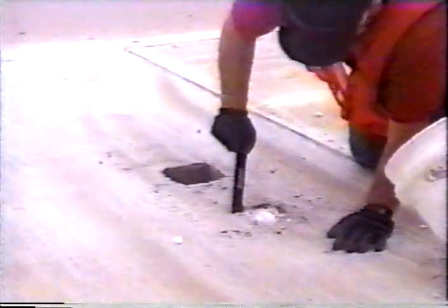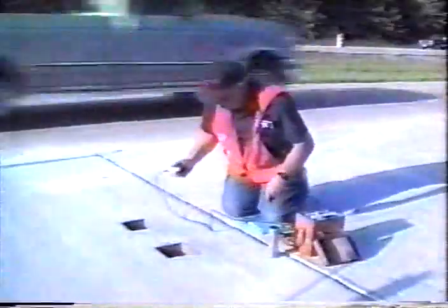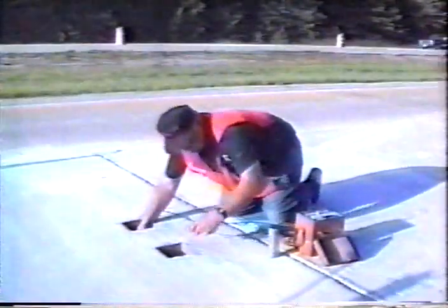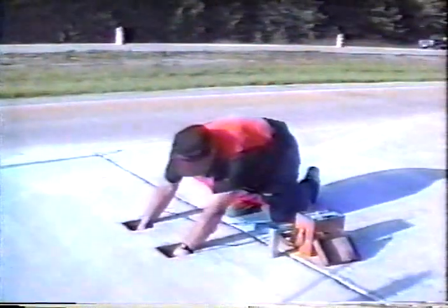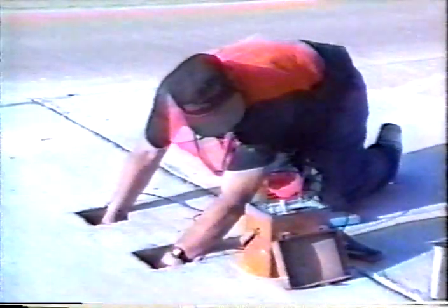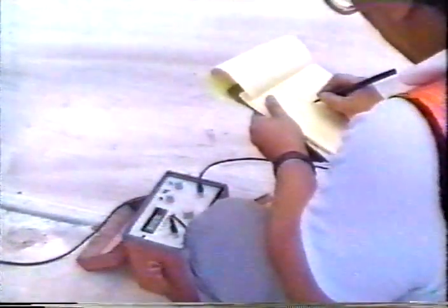The blocks are removed once the concrete has set enough to not be damaged. After block removal, the travel distance is measured and the transit time is measured using the pulse velocity equipment. The transducers should be positioned directly across from each other at the same elevation. The pulse velocity is computed, and the in-place slab strength is then estimated from the velocity using the relationships developed earlier.